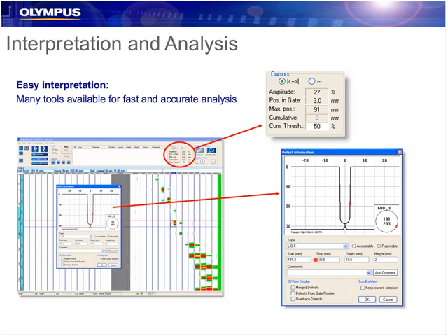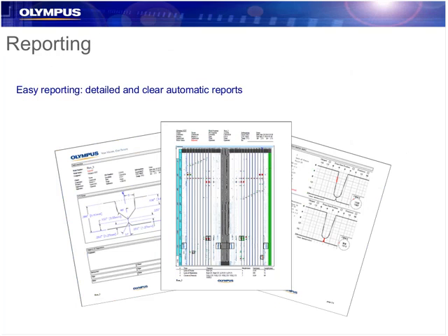Here is a close-up example. In this case, we have one zone selected, one defect, called lack of fusion. I have the start and stop or length, the depth, and the height. I can add some comments, do different things about merging defects, which is more complex, or just add it to the report. In the sample report, we can get all the bevel design, the cow block design, everything imported directly, and an illustration and additional information about each defect.